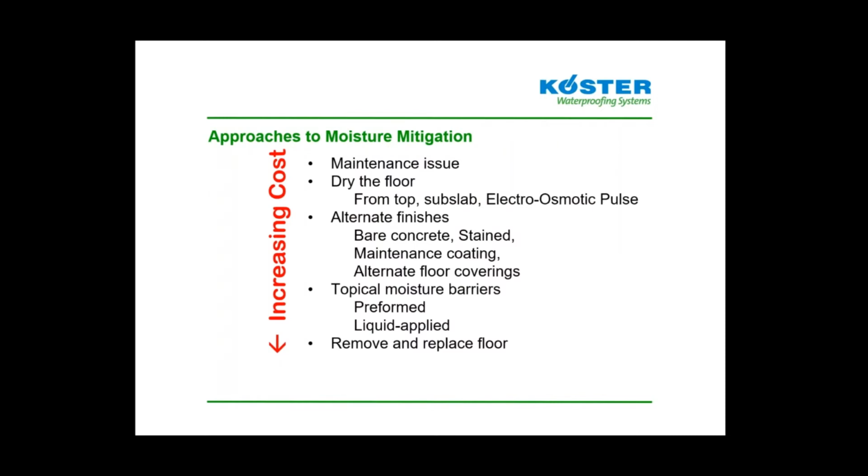So once we know that a floor slab has high moisture conditions, there are many options to treat the floor. This slide indicates a couple of the options which range from low cost to higher cost. Floor slabs may have sporadic, isolated moisture problems that can be treated by repair locally as maintenance issues. An owner may accept the contractor setting aside some money for maintenance rather than interrupting the entire business and treating